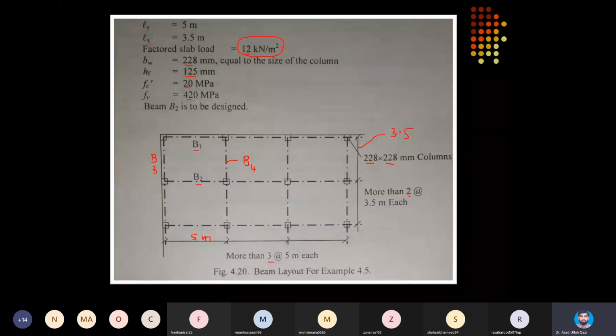So according to the thickness of the floor finish proposed by the architect and the type, you will select the densities and then you will determine the pressure load. Also, knowing the type of building, you will select the live loads. So in this way, after doing this exercise, you will get this 12 kilonewton per meter square, which is given directly here.